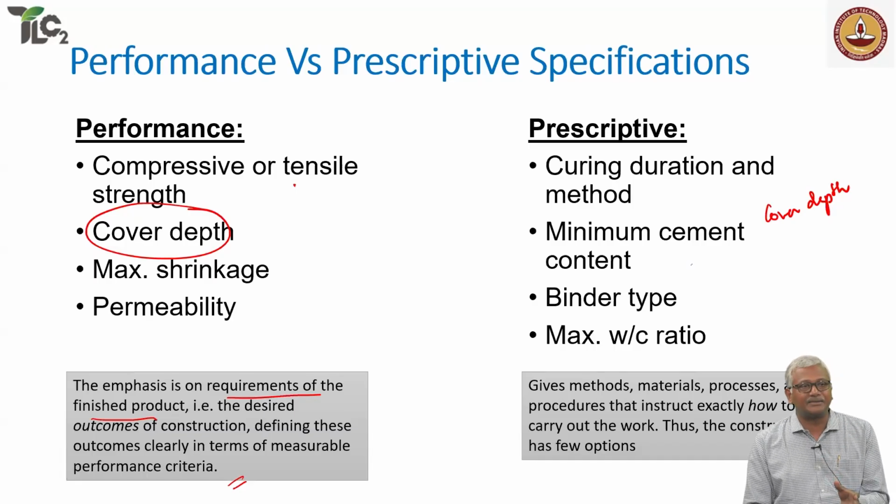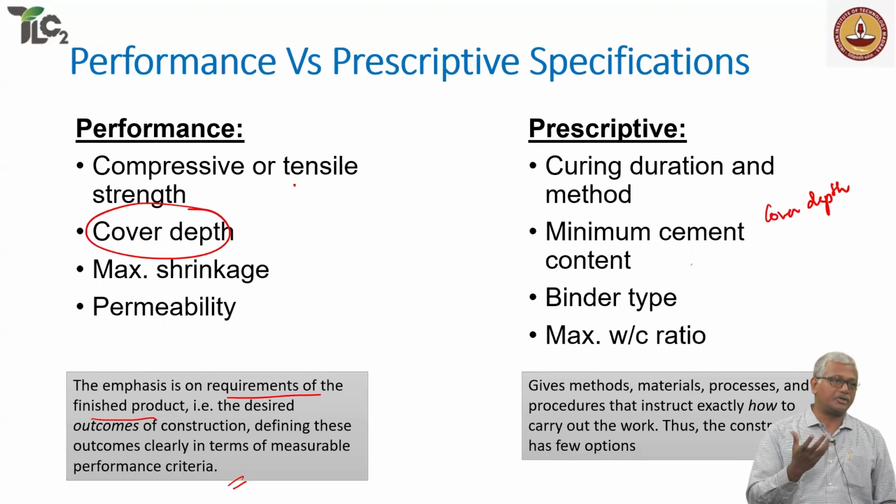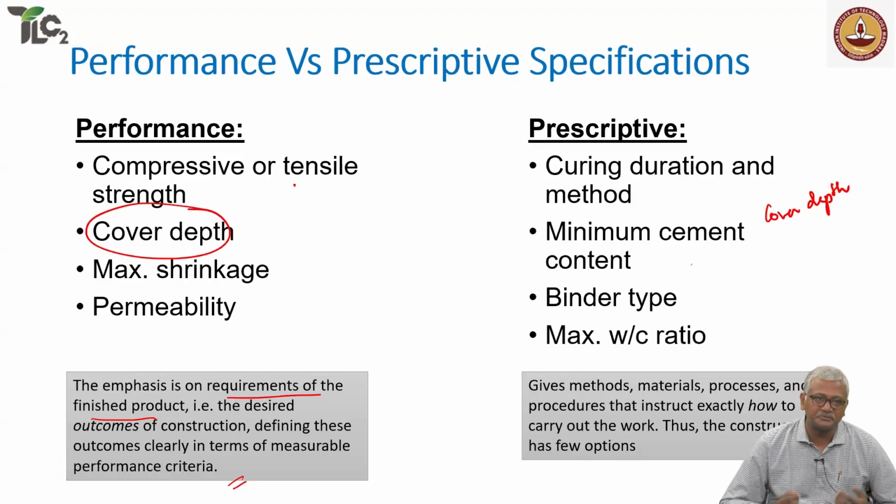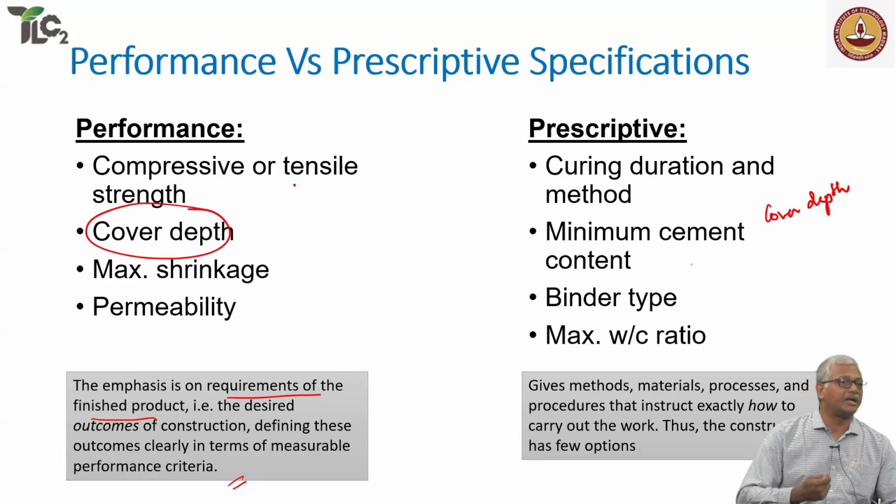How do we ensure that what we set as a performance parameter gets implemented, and how do we take action when the required quality is not met? For strength, we understand it's not a big deal, right? If a column concrete shows lower strength, both in the specimens and in the cores, we say, okay, do a jacketing, increase the capacity of the column. Simple enough, right? What do we do for lack of required impermeability in the concrete? Then we have to start looking at what is an option for coatings, which will reduce permeability, right? How do we reduce the water penetration characteristic? All of those things need to come into play when we start thinking about how to implement durability specifications.